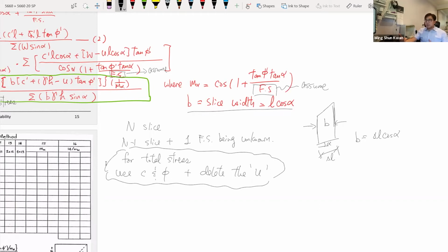I got the unit weight of the soils correct, and the friction angles, the strength test, the triaxial test. Make sure all the soil parameters are correct before I start this analysis. That's why soil strength is very important to visualizations. Nothing is correct at the beginning if your input parameters are wrong already. So you need to make sure all the soil parameters are ready. Think about whether there should be drained or undrained conditions.